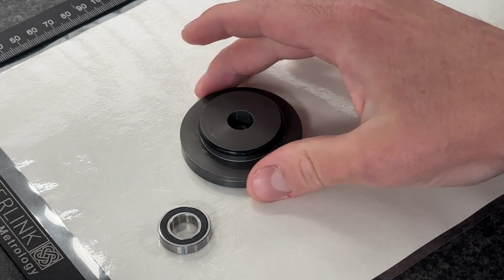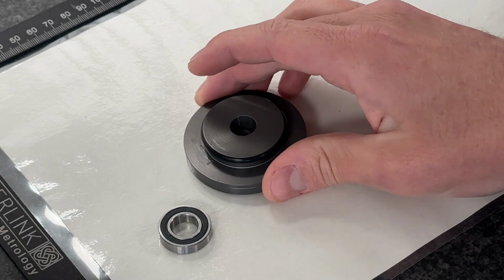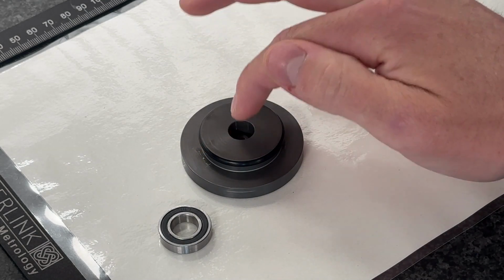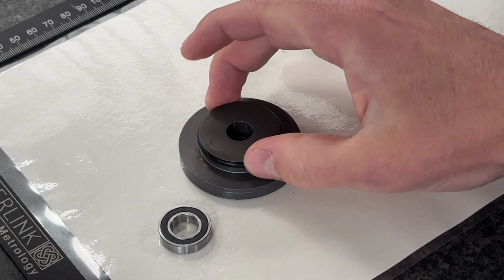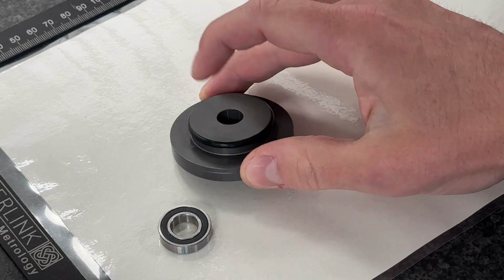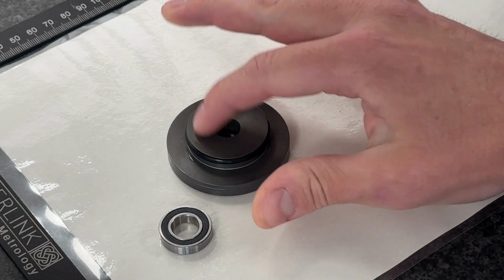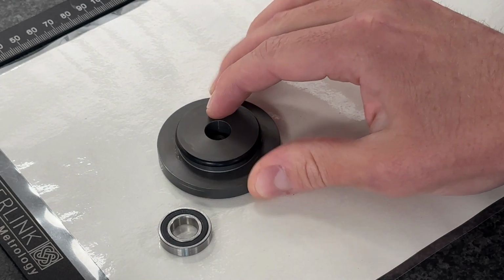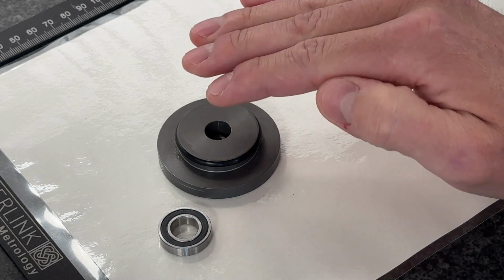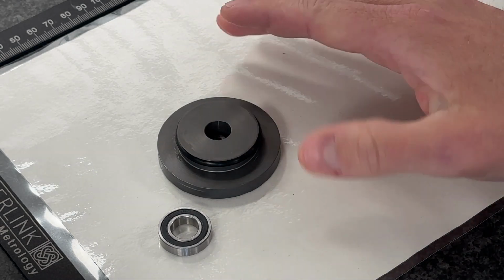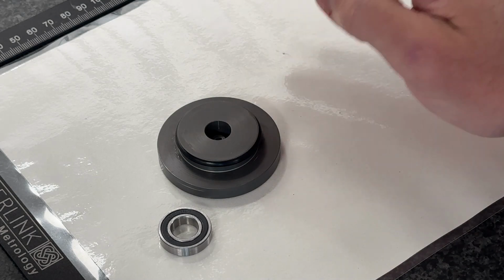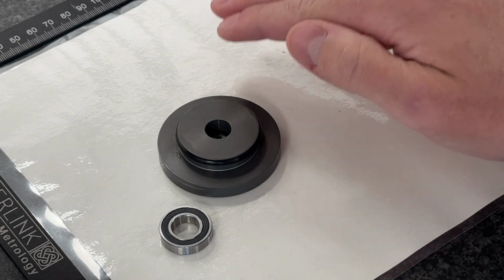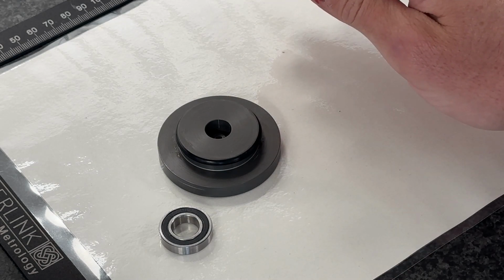Another good example is one of our air bearings. We need to verify that the central hole for the spring lines up with the O-ring seal, and you can imagine they would both be measured from this face around about 1 millimeter down. So they're both being measured at the exact same height, meaning there's no axis line skewing occurring on the part, which would give us a varied measurement depending on the height that we measure it at.